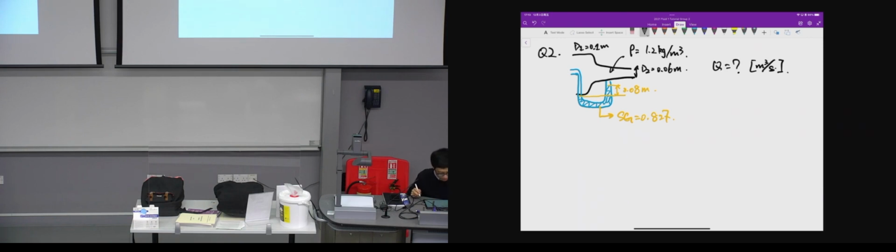All right, so here we have a very typical manometer, but when we apply a manometer, we need to first identify which pressure it measures. For the tube at point 1, and point 2, for the pressure at point 1, since it's in the same direction as the flow, it measures total pressure.